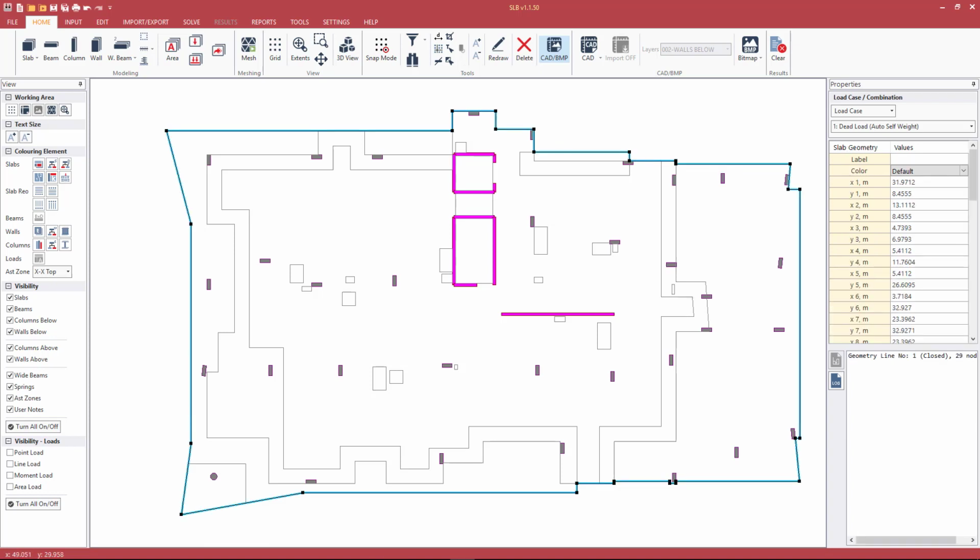So this level of accuracy may be needed to generate a structural drawing or an architectural drawing, for example, but it's not needed to capture the structure's behavior, to capture its structural response. It also makes the model much more difficult to edit and basically makes it sensitive to meshing errors. So it's generally a bad idea to use this high level of accuracy in any Finite Element software. So before we continue, the very first thing that we'll do is we'll round off the geometry. So rounding off to 1 or 2 decimal places is recommended, and if new to the software, rounding off to 1 decimal place or to the nearest 100 millimeters is recommended.